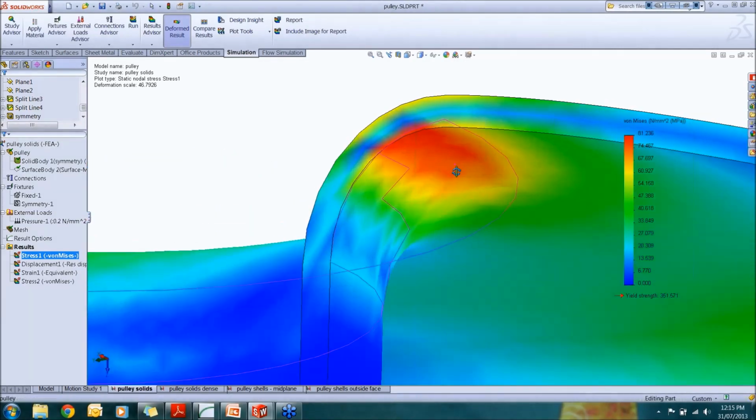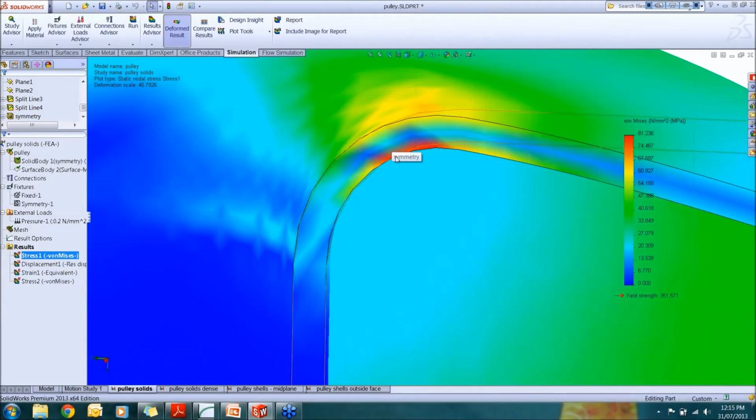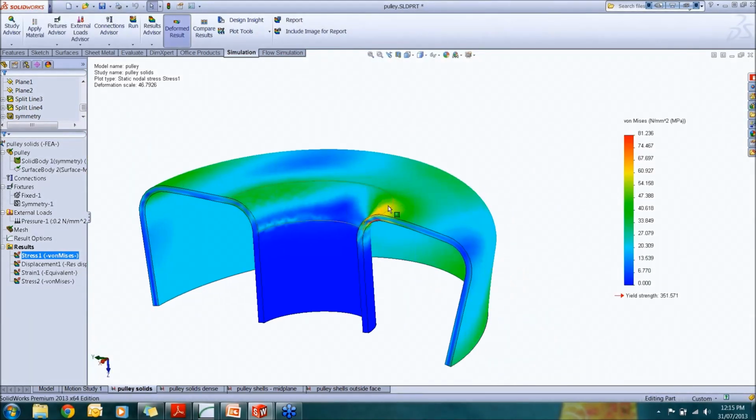Zooming in more, you can see a very coarse transition from the back or inner surface to the other surface, and there is a very rough interpolation of von Mises stress here. So that brings our attention to the fact that what we have generated here is not that accurate in terms of magnitude and distribution at the same time. So we have to reconsider this analysis with a higher number of elements.